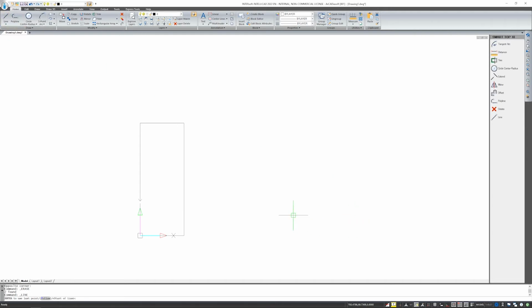The first value is exactly the same, but now when introducing the next value, remember that you're starting with an at sign again, but now this is the beginning of the coordinate system, which means that if I draw up, for example, in x, there will be no displacement. So I start with 0, the comma, the value in y, it was 500. And in this way, every time starting from the at sign, I enter the appropriate data relative to this exact point. So now again, when it comes to the horizontal element, it will be to the left, which is minus 200, comma, 0, because I'm going horizontally.